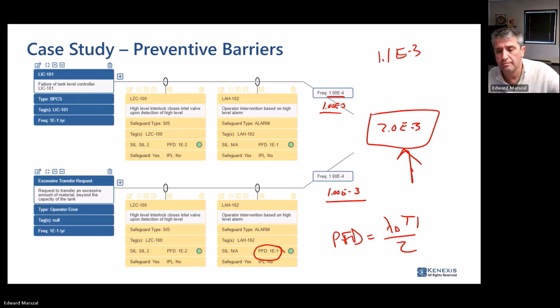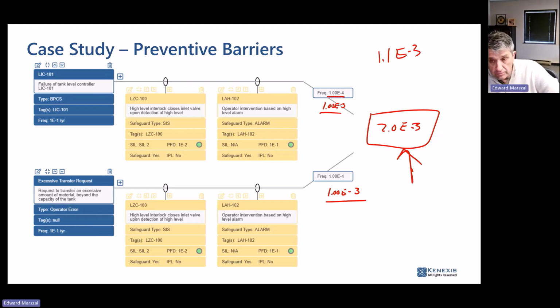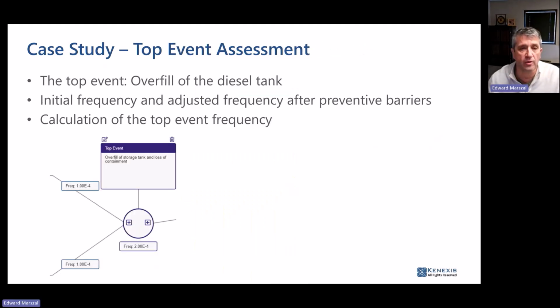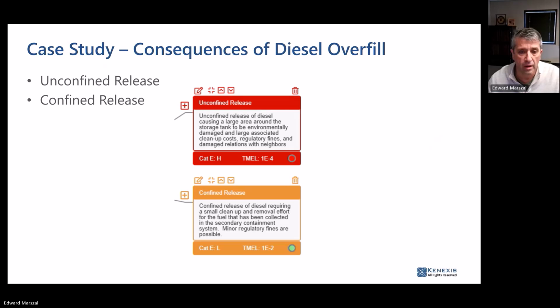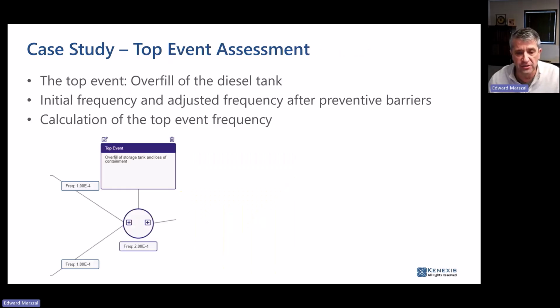In this case, in the end, I have to aggregate, I have to sum up all the risk reduction factors. No, this question is related with the one of Francois, because maybe he was asking not about the PFD. I totally agree that is not going to change, but this final frequency, or in this case, in a LOPA study, the risk reduction factor, you have to aggregate this final risk reduction factor. Yes. Of all the scenarios. Right. So the same that you have done with the frequency. So in the quantitative bow tie, we are doing an aggregation.